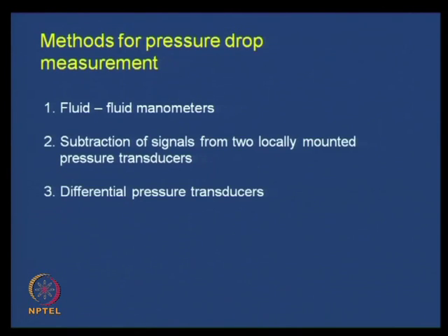For liquid-filled cases, we very frequently see that micro manometers etc. can also be used for better measurements. Then the other technique, as we have already seen, is subtraction of signals from two locally mounted pressure transducers, and after that the differential pressure transducers. It is not the case that one particular method among these is always the best.